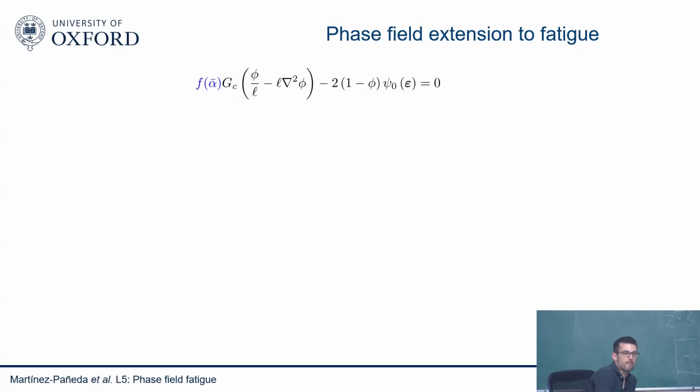Yeah. But the same argument can be made even for a brittle material. Once the crack starts, of course, it goes completely, but the fracture toughness goes down. So 1 minus phi. But does it really go down, the fracture toughness of a brittle material, in the sense that it's a material property that remains the same? It's just your driving force goes up, right?